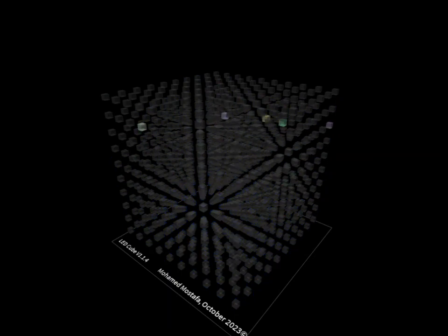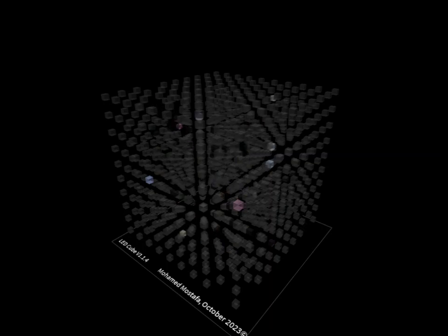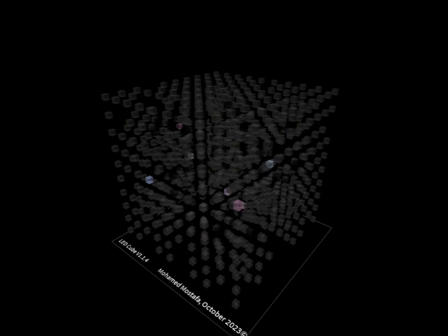We gathered from the last step that an 8x8x8 LED cube requires 64 plus 8 I/O lines to operate. No AVR microcontroller with a DIP package, the kind of through-hole chip you can easily solder or use in a breadboard, dual inline package, has that many I/O lines available. To get the required 64 output lines needed for the LED anodes, we will create a simple multiplexer circuit. This circuit will multiplex 11 I/O lines into 64 output lines.